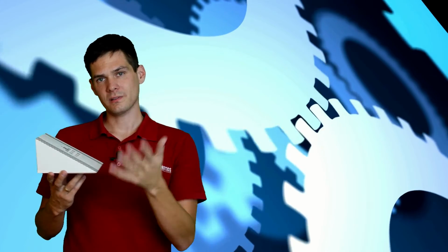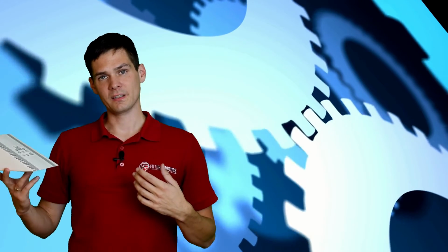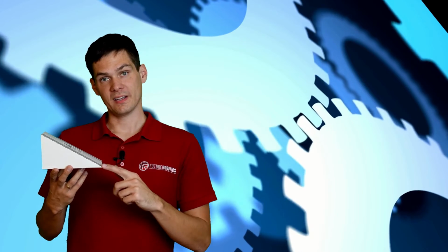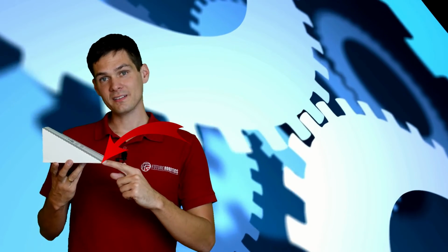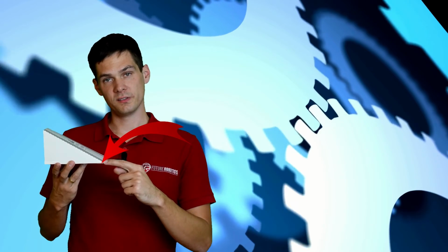But what you're interested in is where it is located in here. Because you don't really care, I can be here, this can be here, wherever, right? So that's why you will teach the base, and you're going to define the 0 of the base, the origin, in one spot. So let's say here, right? You're going to teach that spot here, and that's going to have your coordinates of 0, 0, 0.